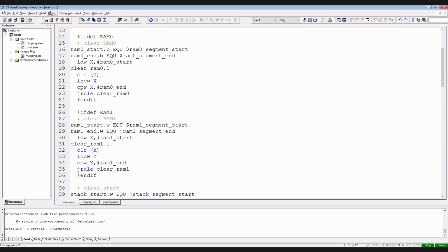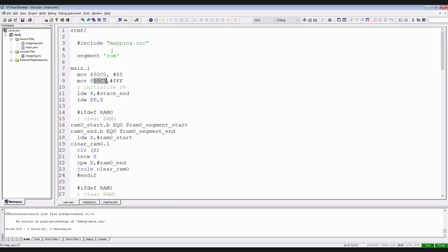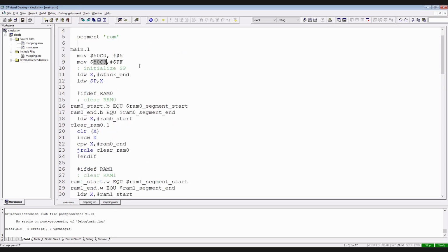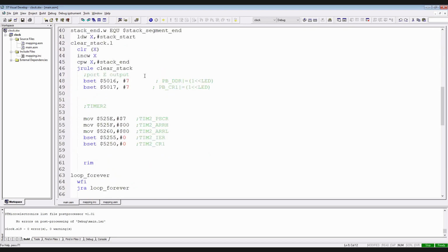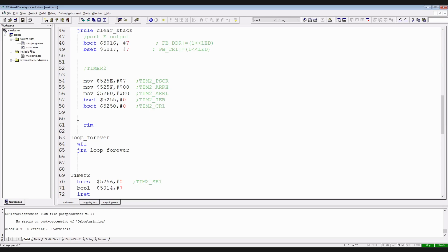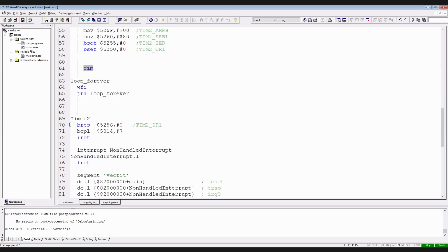In this case, it's quite hard to use the internal simulator and the plotter. You can use the debugger mode to, for example, check the reset the interrupt flag behavior, but normally it's hard to simulate the interrupt behavior in STVD.